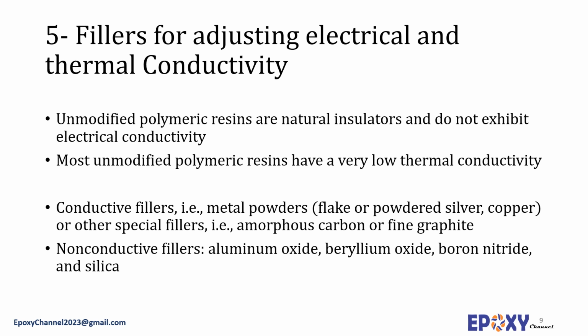Electrically conductive epoxy systems owe their conductivity to the incorporation of high loadings of metal powders or other special fillers. If enough metal particles are added to the network within the polymer, the matrix becomes electrically conductive. Currently, all high-performance conductive products are based on flake or powdered silver as it offers an advantage in conductivity stability that cannot be matched by copper or other lower-cost metal powders.